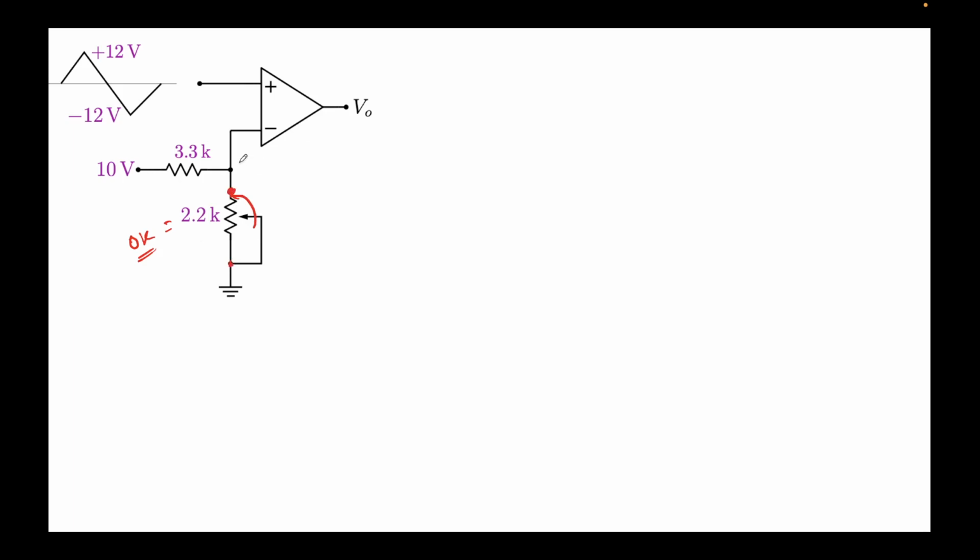So what I'll do, I'll simply try to find out what is this Vref. Note that this input voltage will compare it to the Vref, right? So as a step 1, in top position, find Vref. How do you find Vref? So there's no current flowing here, so all the current will be flowing like this, correct? So Vref will simply be 0. Note, this potential is the same as this potential, right? So if Vref is 0, this means now we can draw the output waveform.